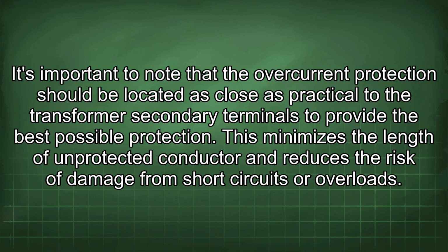It's important to note that the overcurrent protection should be located as close as practical to the transformer secondary terminals to provide the best possible protection. This minimizes the length of unprotected conductor and reduces the risk of damage from short circuits or overloads.